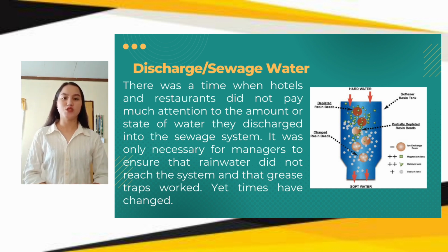Each of these resin spheres contains sodium ions, which are exchanged for calcium and magnesium in the water. The reaction is nearly rapid and complete if exchange sites are accessible. When all the exchange sites have been used, the influent begins to harden, which is referred to as breakthrough. So the breakthrough necessitates the renewal of the medium by exposing it to a concentrated sodium chloride solution.